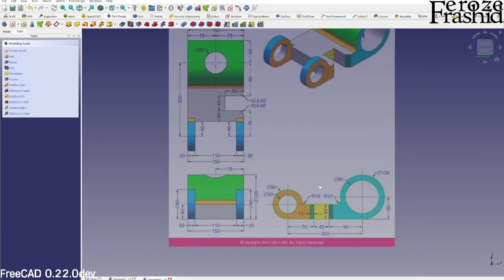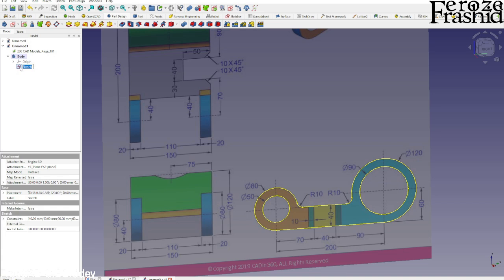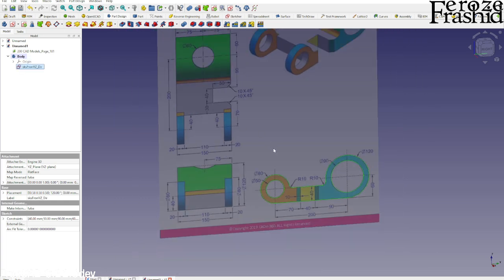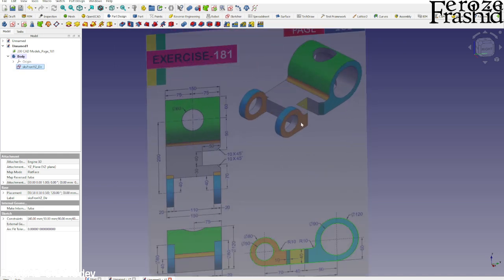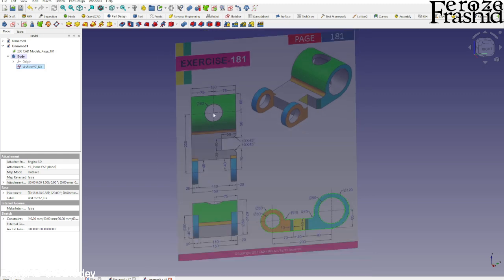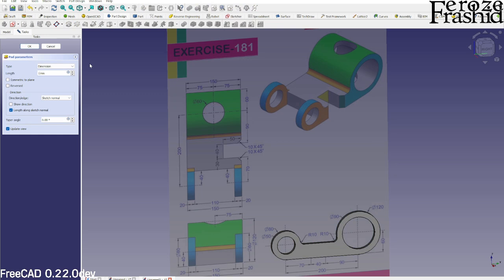All right, so now we got this sketch, right? So that's the sketch. Let's rename the sketch to 'from YZ direction'. All right. Now there is a decision to make. Where do I want to make this sketch? Do I want this on this face and then push it backward, or do I want it in the middle? Given that there is a circular hole that I'll have to draw later on, I'm inclined to keep it in the middle. So the pad will be 150 millimeter length of this sketch, and I want to make it in the middle so it would be symmetric to the plane.